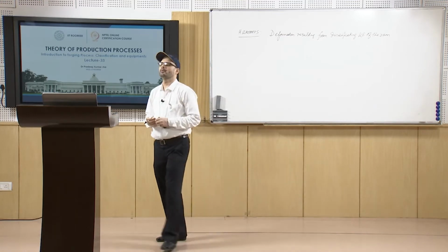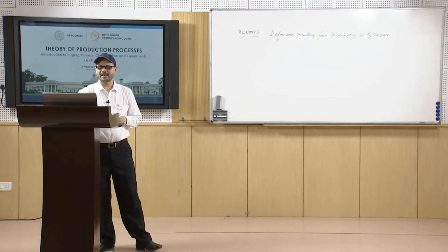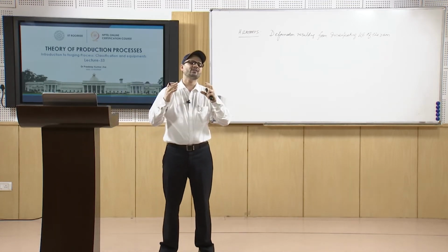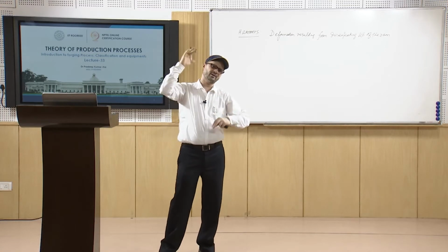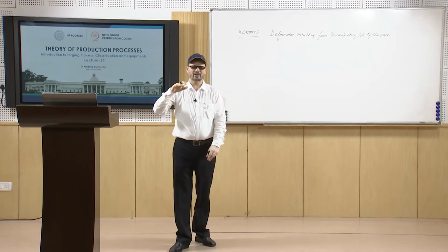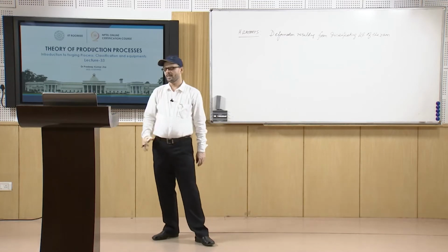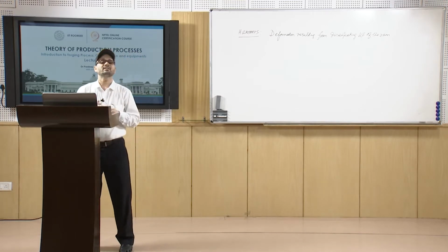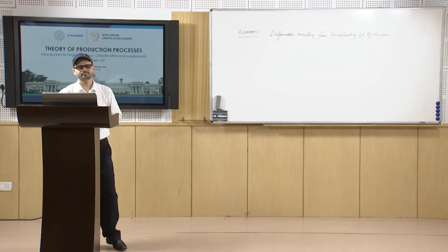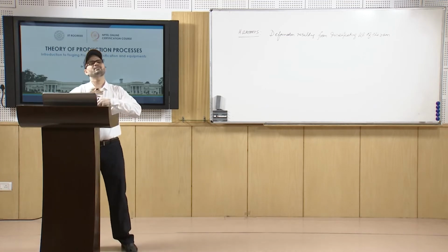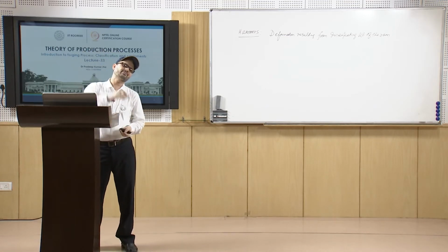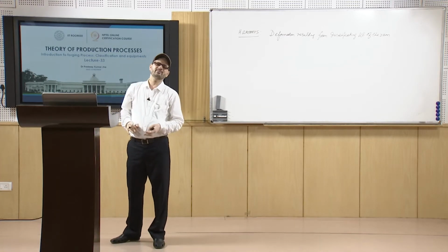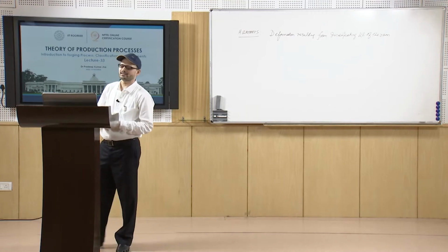Using that, while the hammer is moving downwards, you can give extra velocity and extra pressure to generate extra load and extra energy. That is the concept of the power hammer. Steam or air pressure is also used to uplift the ram after striking.